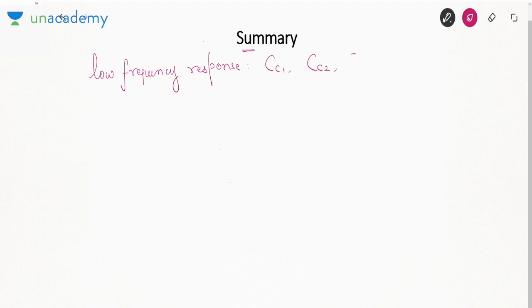CC1, CC2 and CE. Then in high frequency response, which capacitances are considered? Diffusion capacitance and transition capacitance. And how to find cutoff frequency? 1 by 2 pi into RTH into C.